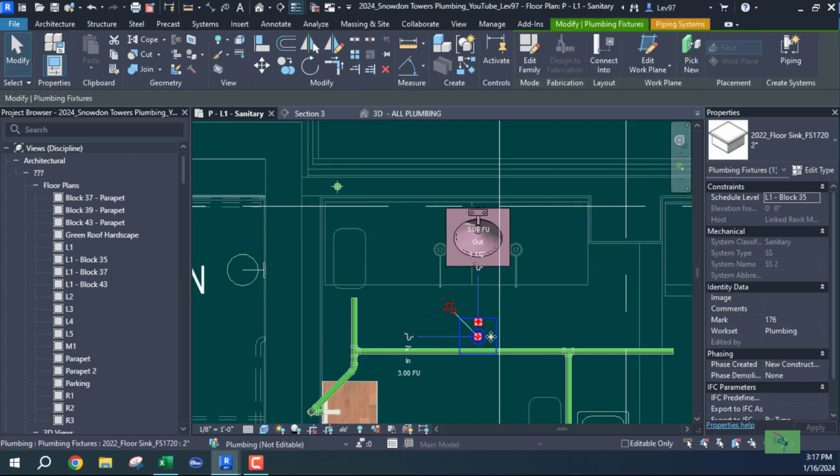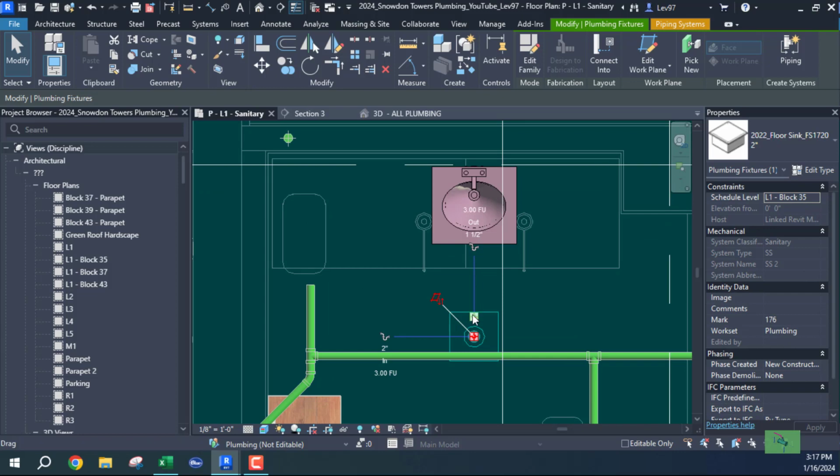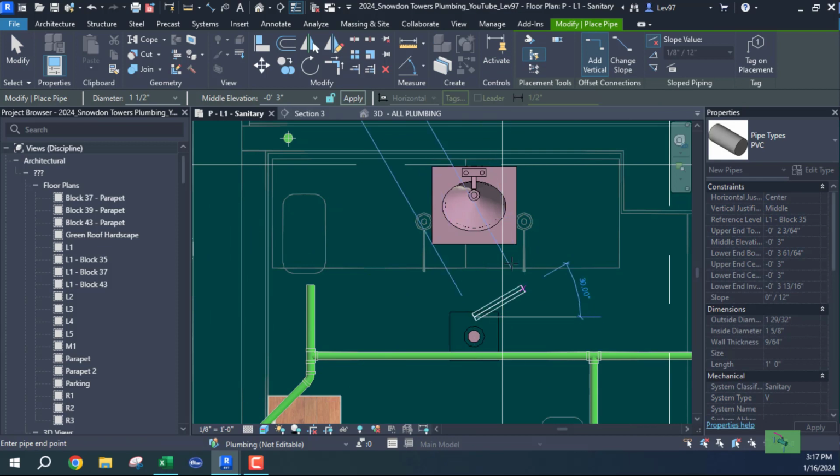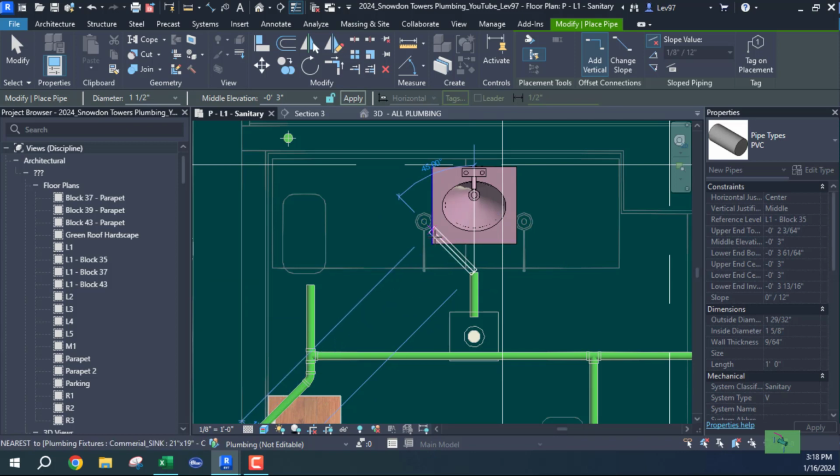Let's do the floor sink. The floor sink has a trap, so it needs a vent, okay? So we're gonna come here, and we're under the floor, and somehow they have to trench this out, or however they're gonna build this. And this is just a diagram, you know, this is not a shop drawing or anything like that. So this is just a diagram, just like, let's pretend it's AutoCAD. It's not real, right? So I'm gonna bring this out, and I'm gonna offset it 45. Offset 45, because of what I'm gonna do.